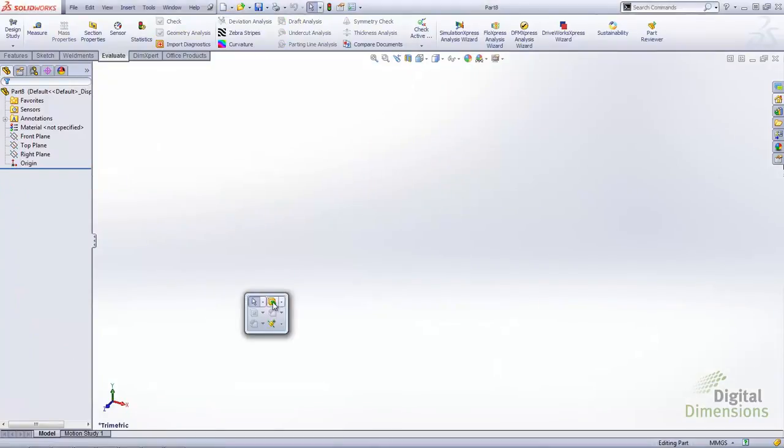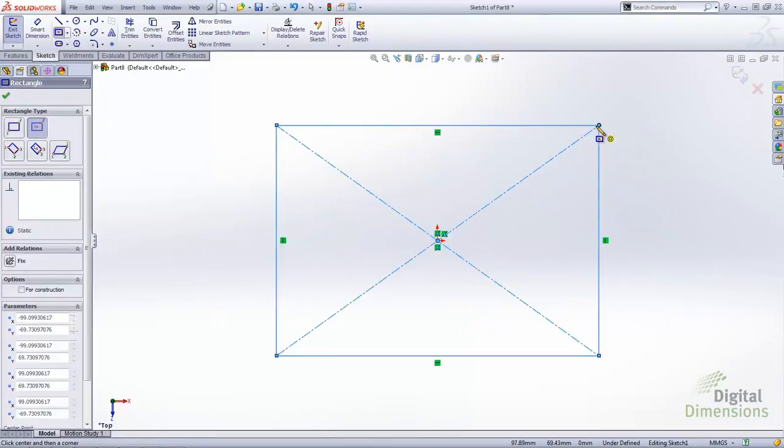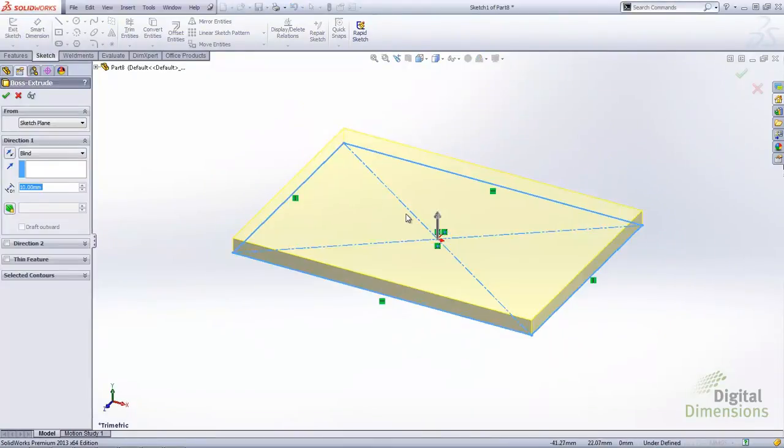With SOLIDWORKS 2013, we've been given some additional utility for global variable creation. We can now create global variables during feature creation. This is done by simply inserting the equal sign and naming the global variable. When naming the global variable, you see that you have the ability to create global variable. Clicking that icon will give you the world icon, denoting that the global variable has been created.